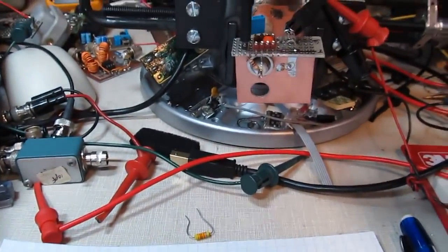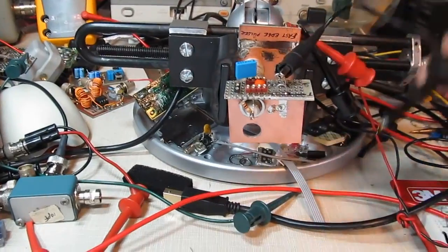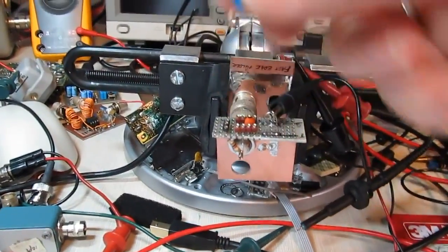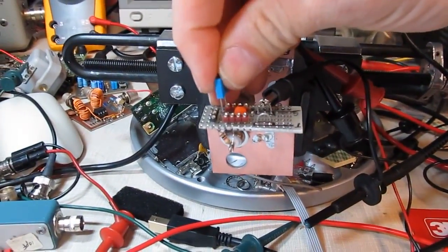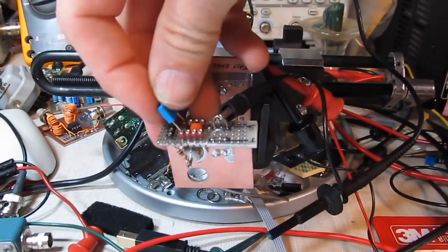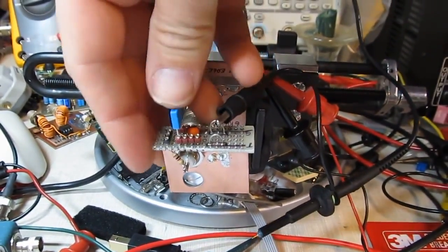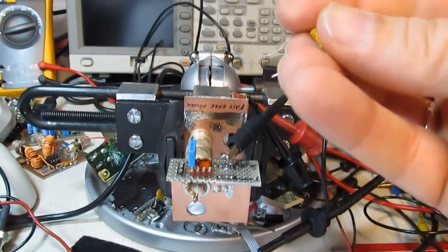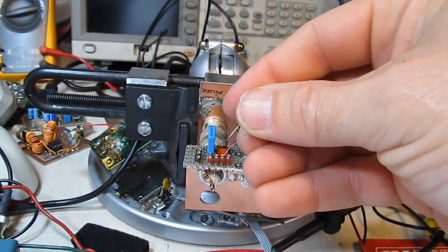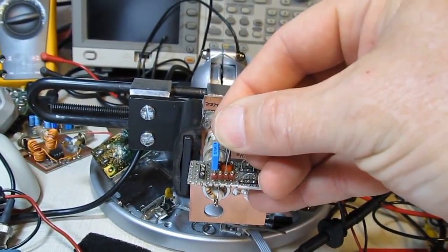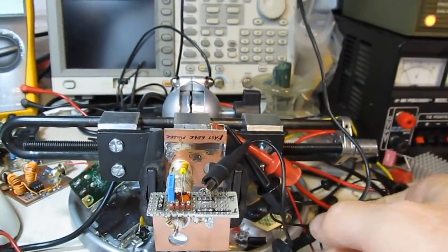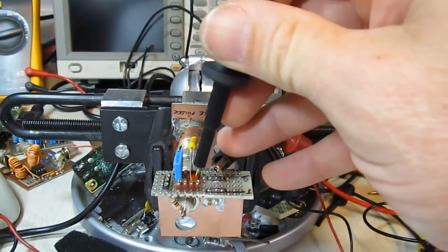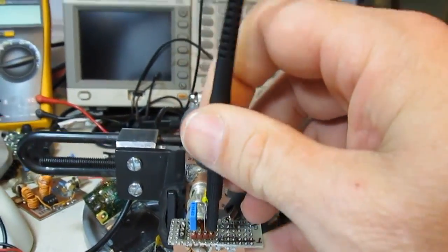Now if we want to measure an unknown inductor, let's just say this is our known capacitor of 1 nanofarad. So we'll stick that in the fixture here. Just have to do this with one hand and hold the camera. And let's take my quote-unquote unknown inductor here and stick that across here as well. And now I'll stick my probe in here to measure the response of that circuit.